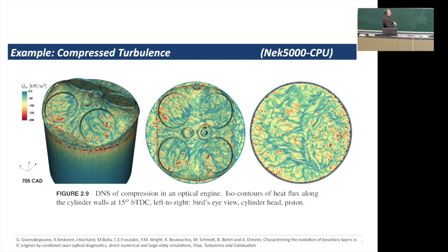Finally, 5-10 years ago, we were able to look at and solve this problem. And of course, when I tell you the answer, for those of you who are fluid dynamicists, it will strike you as obvious. But the turbulence scales really go up at top dead center, and then they fall away as you expand. And one way to look at it is the Reynolds number goes up because the density goes up. That's the easiest way to look at it. Another way to think about it is you're under isotropic compression. You have a vortex, and you pull your arms in, you spin faster.